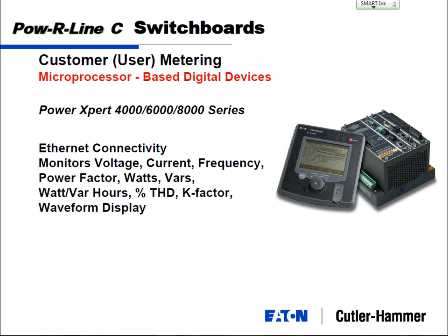Fine and dandy if those guys exist, and even in the best condition, they're guessing on what happened. So today, one of the things they're doing retroactively is adding meters around the airport in select locations. If an event does happen, they've got some means to pull up some data and go, okay, this tripped first, then this tripped, so we know the fault started here and propagated to here. And you put those pieces together to figure out what happened.